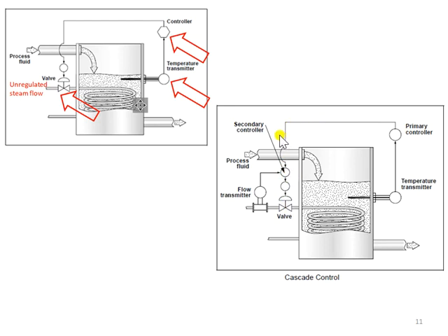So this is a very important criterion to distinguish between a cascade controller and other controllers. We can see that here the output of the controller will be the valve opening, but in the cascade controller, the output of the primary controller is no longer the valve opening, but now the output of the primary controller is the steam flow rate.